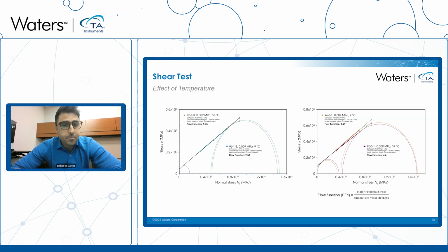Shear test. This is what Trios gives you guys. You remember I mentioned 5 plus 1 points. We have the 5 shear yield stress points here from the reducing normal stress. So we fit a line to that. We call that the yield locus line.